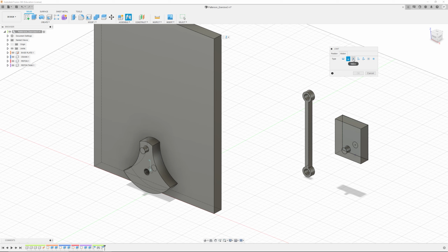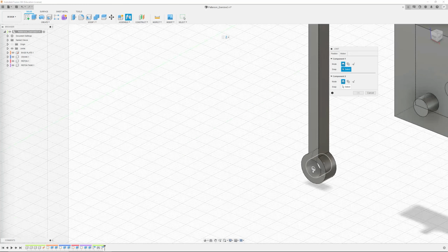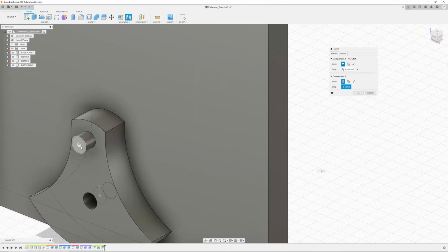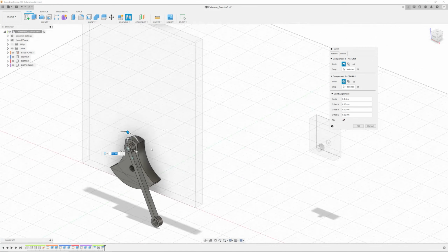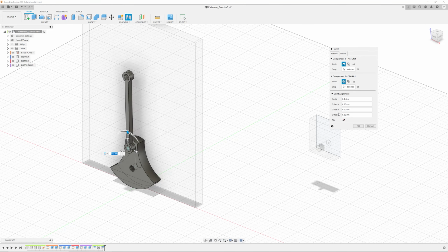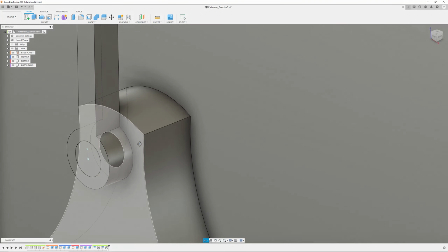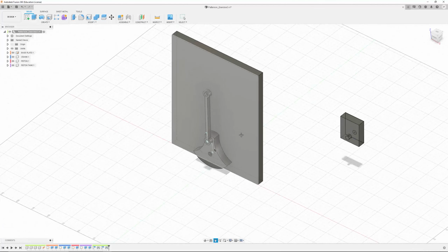So this one is probably something like rotates around and moves along a simple axis. Well, I guess we can try revolute and see if that works, and then we'll go from there. So I'm going to click that point there, and snap it to this point there. That's what we want to see. Hit OK. That one lines up perfectly, so that's good.